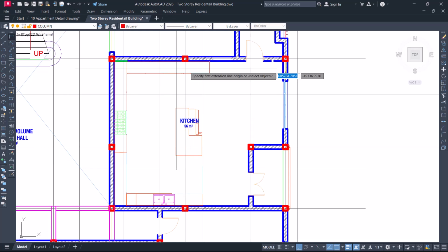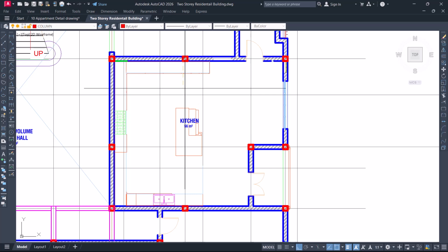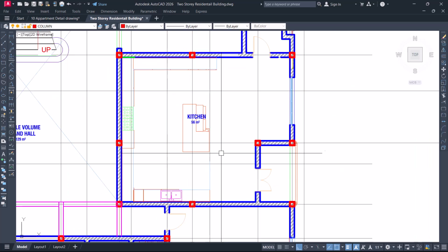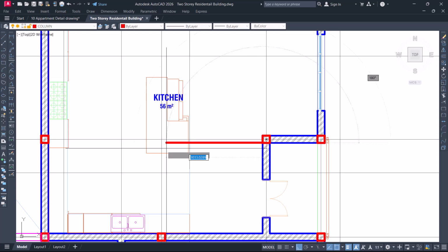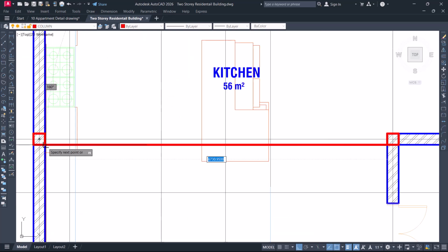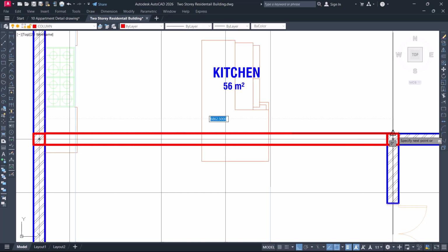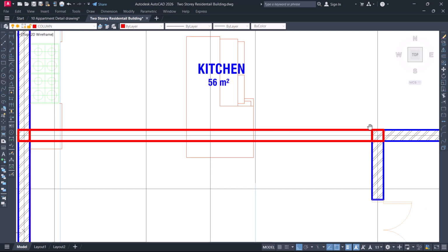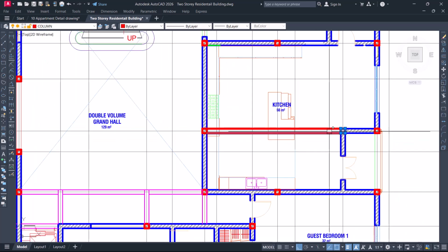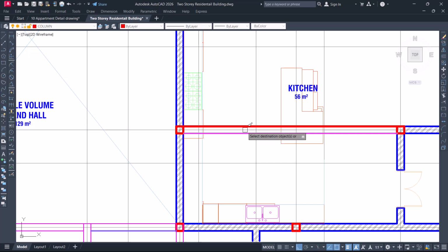So from here to here, we'll have, let me see, 7 point something. So I will take this as my beam to break this panel. I will create an internal beam here just to break the panel, and again here. This beam will be deep actually, and the columns carrying this beam will be big. They won't be this size, but let us use the effect to design for it, because right now we are just assuming the column sections.